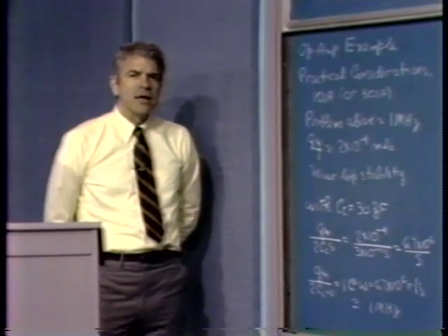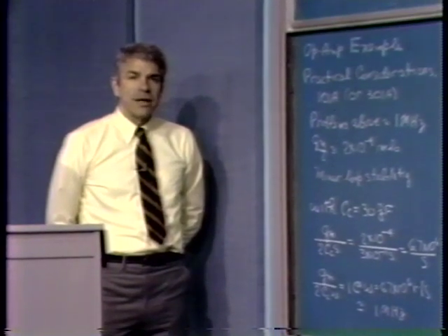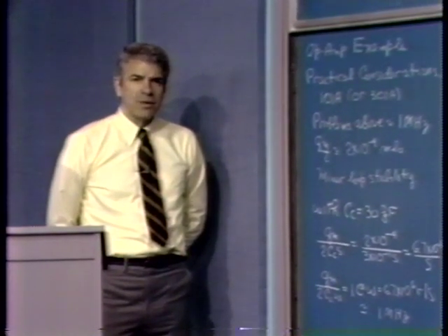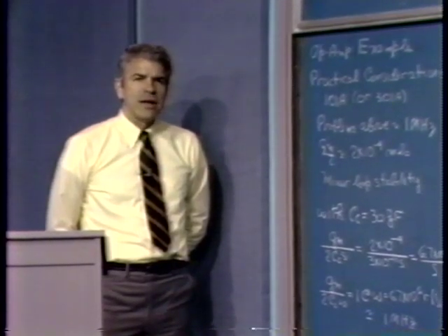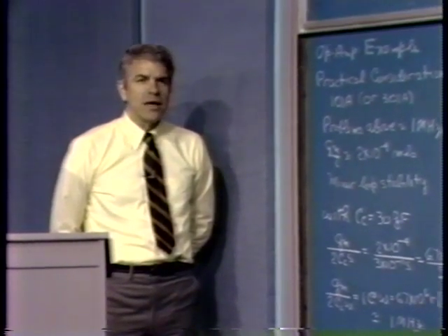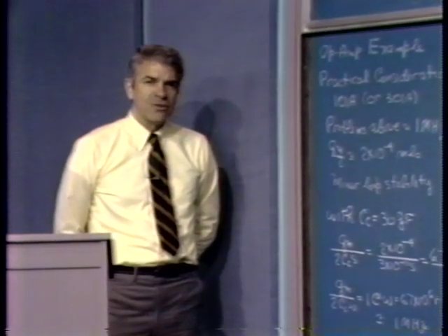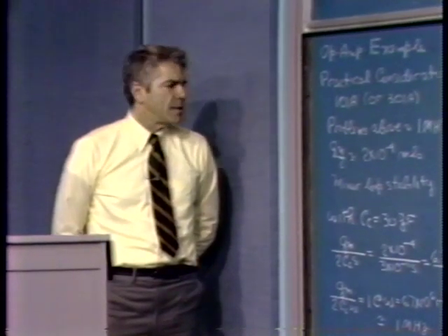The reason for that has to do with poor dynamic performance associated with the lateral PNPs. In particular, above about a megahertz, they look very much like time delays, and we're not able to compensate, as we recall, for the phase shift associated with a pure time delay.